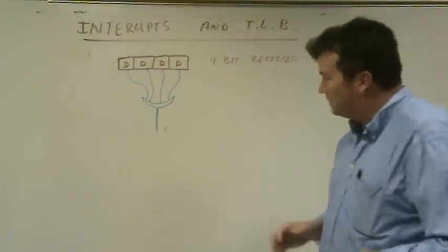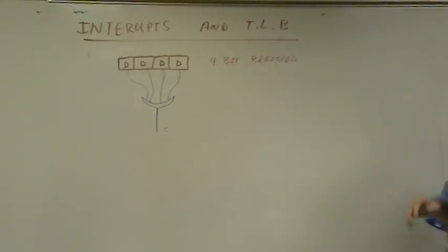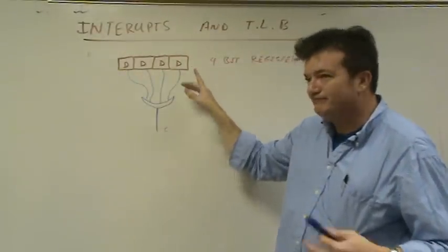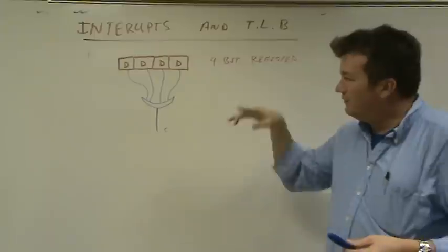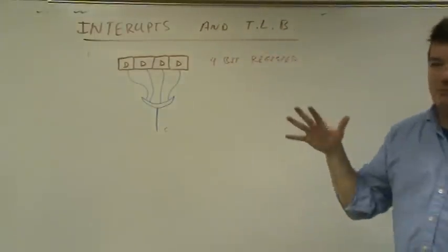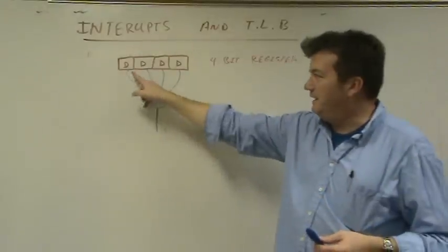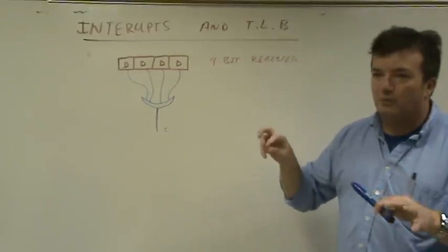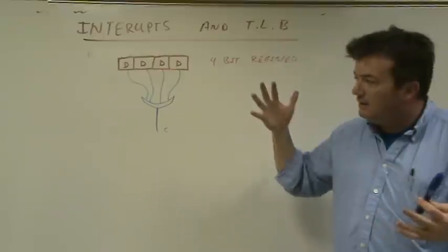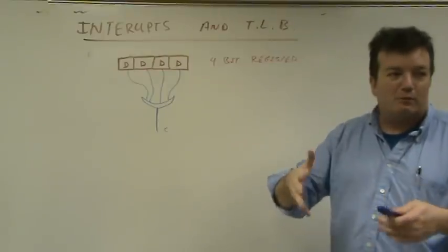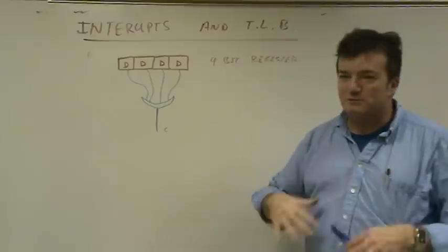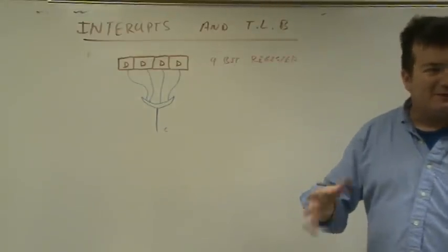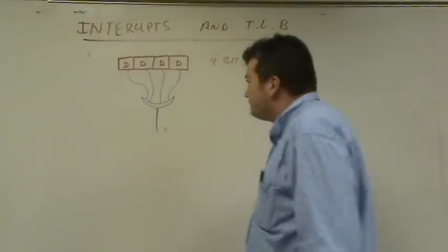When could this be used in the real world? Suppose we had a particular register where a 0 here means there's no action to be taken, but if some number gets put in here, 1 up to 15 is what a 4-bit register can hold. 0 to 15, but let's say 0 means there's no problem, but if some number 1 through 15 showed up, we'll consider those problem 1, problem 2. And this line will come on, which means we have to handle a problem. And if this line is off, there's no problem to handle. So it could be used for something like that, right?